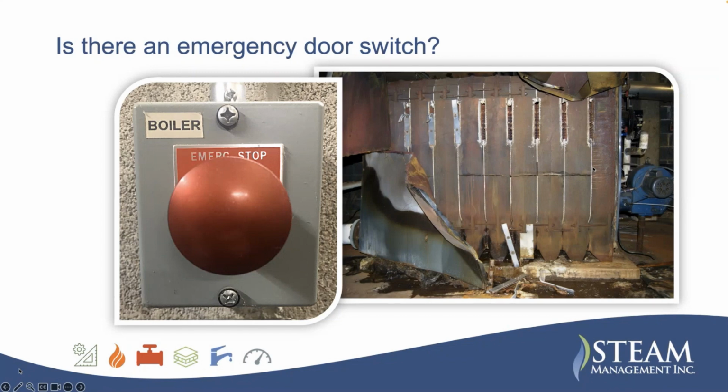And they're lucky it didn't explode and take half the building with it. But it cracked every section, and the ones that aren't cracked on this side, they were cracked on the other side. But all of this could have been avoided if the fire department had come in, found the switch, hit the button, let everything cool down, and figure out what's going on. As a result, it was about a $60,000 or $80,000 repair to replace this boiler, plus the dangers that were incurred.